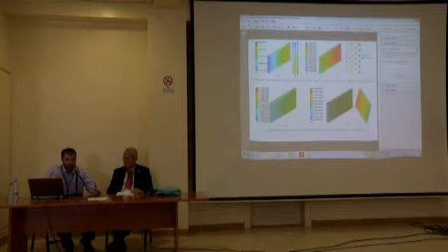And as air crosses this coil, its temperature has decreased, and therefore the heat transfer in the second row of refrigerant will decrease. And here it is predicted in the last figure, now the airflow direction is from right to left. So you notice the temperature gradient decreases as you move gradually through the refrigerant rows. The last figure shows the distribution of humidity and temperature. Again, as I mentioned before, this is the non-uniform distribution due to the non-uniform temperature distribution of the coil surface, and accordingly you can see the variations in the humidity ratio contours.